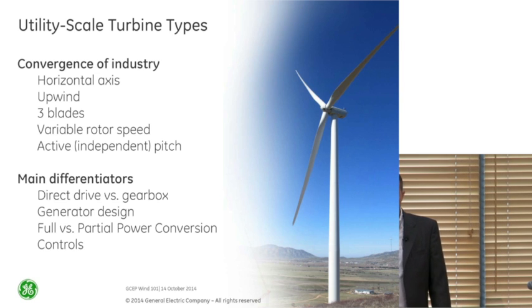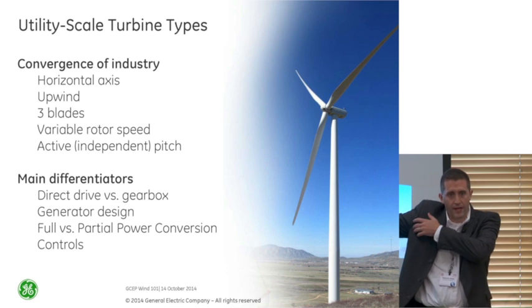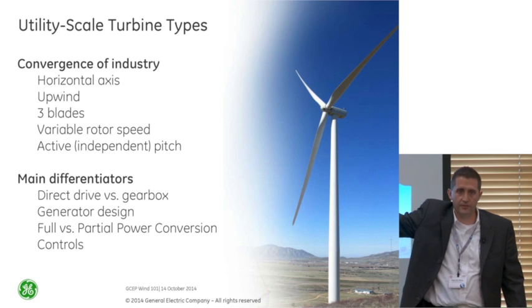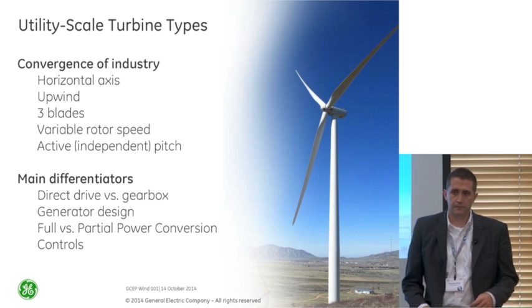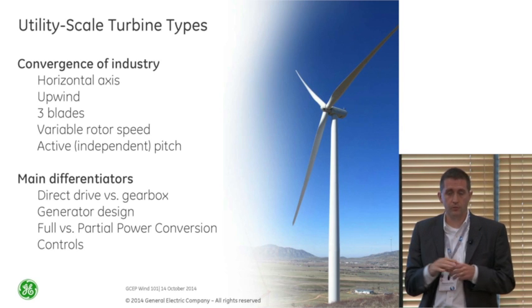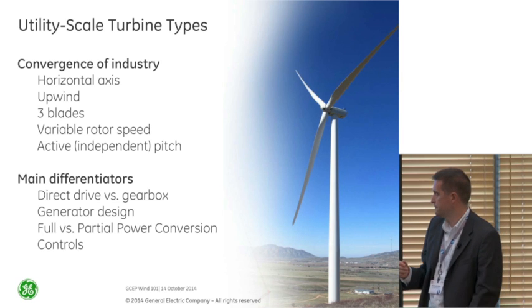So the blades have this aerodynamic performance and they have some sort of shape, but we actually are able to have a pitch mechanism where my shoulder is, and we're able to turn them based on how the wind is. We want to do that to control the rotor speed as well as feather them out of the wind when we get high wind speeds and make sure that we don't create too many loads on our turbine.